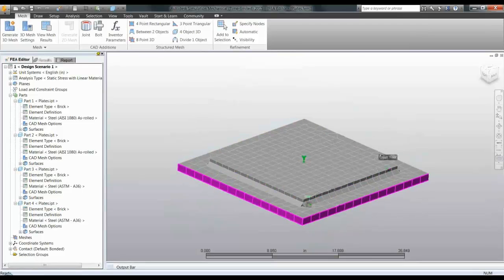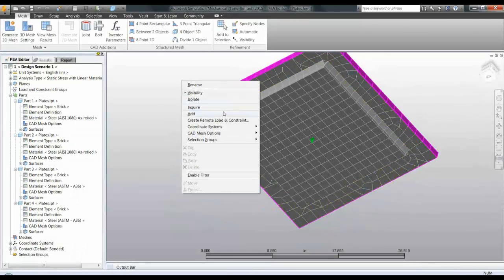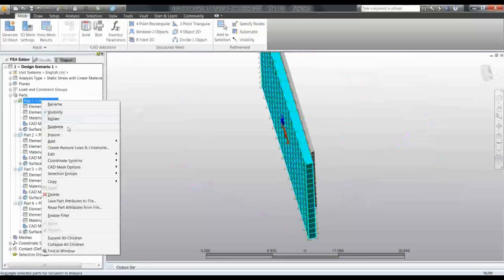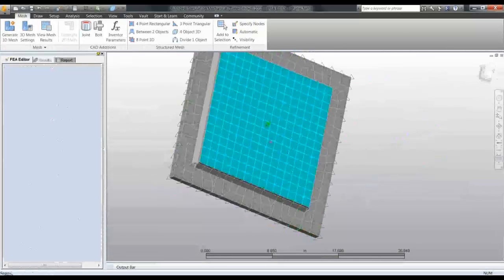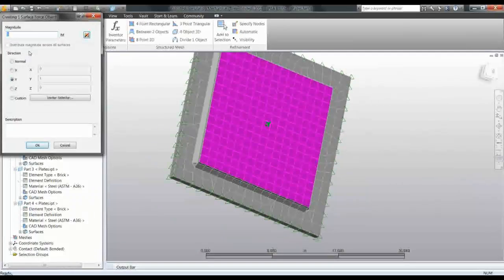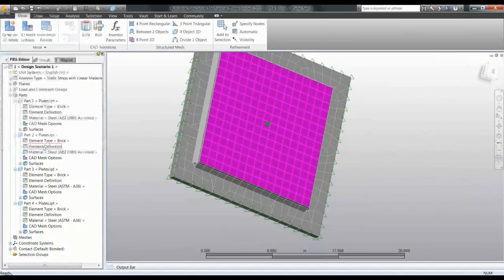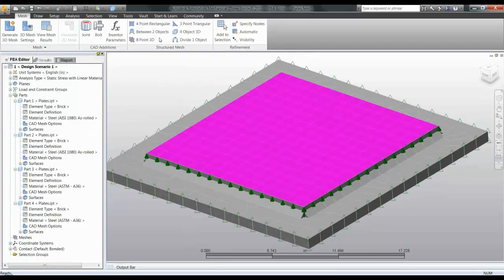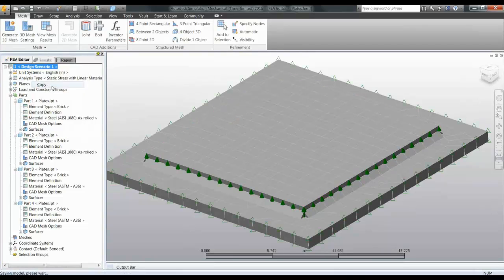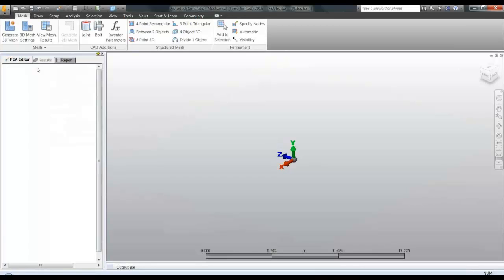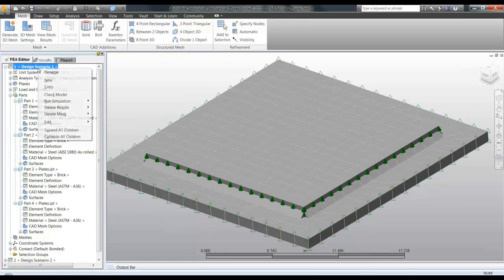Again, boundary conditions, add a constraint here. And then I want to add my load. Add a surface force. We're going in the Y direction, and we're going to do 50,000 pounds. I'm going to clone this right now. Go back to this one here. We're doing 2 analyses here. One's to show the difference between modeling the actual welds and using welded contact.